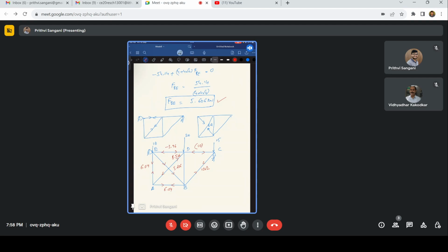So this is going to be 4 times 40, 160, times 11 times 10 to the power minus 6. How much is that? This is going to be 1.76 times 10 to the power minus 3. Is it mm? No, meters. So delta H is going to be 1.76 mm. So this is pretty straightforward.